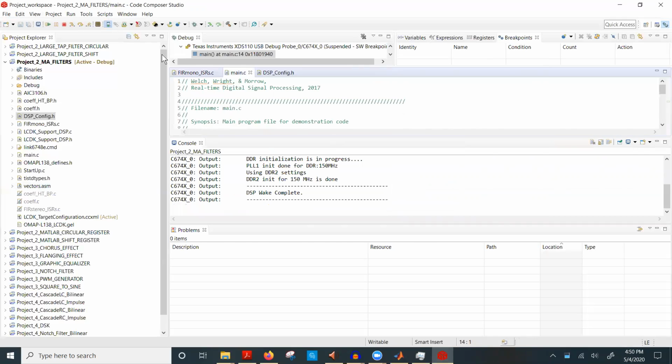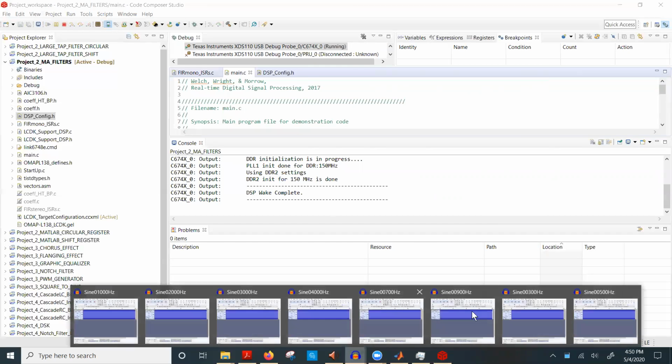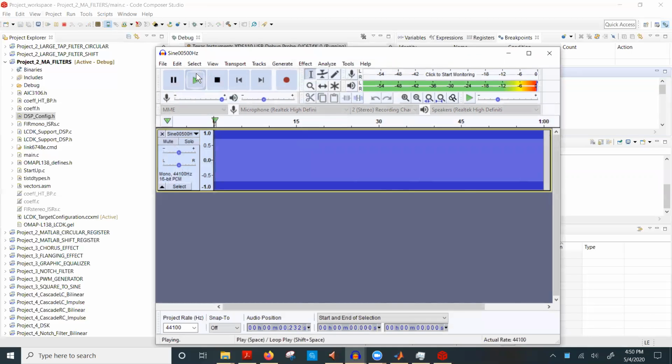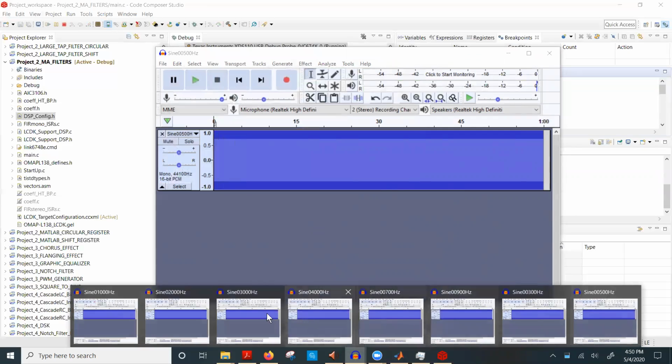And remember, it's a sinc, so that means after it hits that first null, it will bounce back up. So even frequencies above 500 will be there, but they'll be attenuated because they won't be part of the main lobe either. So if I run this, and then I run my 500 hertz signal again, you get nothing because now the first null has been shifted over to 500. If I take something less than 500, it'll be in the main lobe.